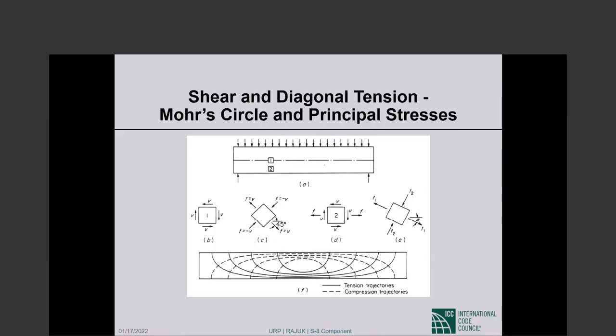Not that we typically do this, but this is very, very important from shear design point of view, because the central point why I went through so much strength of materials is that, remember, one of the first things I told you is concrete is reasonably strong in compression, but concrete is weak in tension. It cannot carry much tension. And we are seeing significant tensile stresses as indicated by the solid lines.